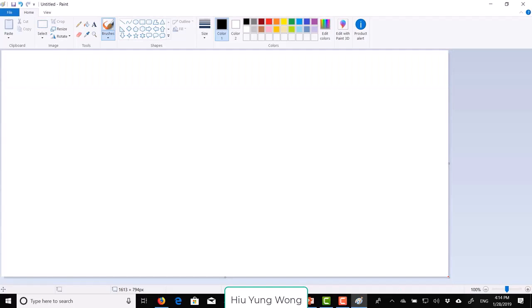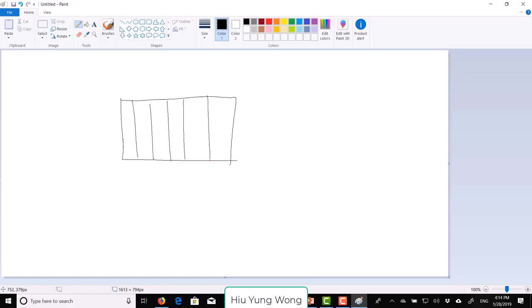For a structure, you actually, like this, right? You have a structure. You actually need to create a lot of mesh. These are the mesh points for your structure. And then the device is going to solve differential equations on this. For example, you're doing a Poisson equation, right? You do this equal to rho. Then you have to solve the differential equation. So you have a lot of mesh points, right?